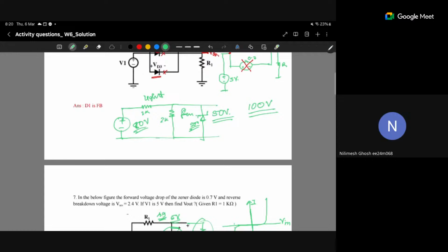At maximum, the voltage drop here will be 40 volt. So this Zener diode will always be reverse biased and will not touch the breakdown voltage, because the Zener diode has a breakdown voltage rating of 50 volt. If you invest money to buy a Zener diode and connect it like this in your home, your money is completely wasted. There is no use of the Zener diode.